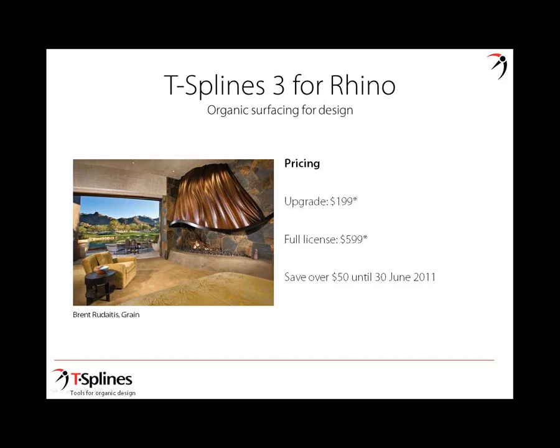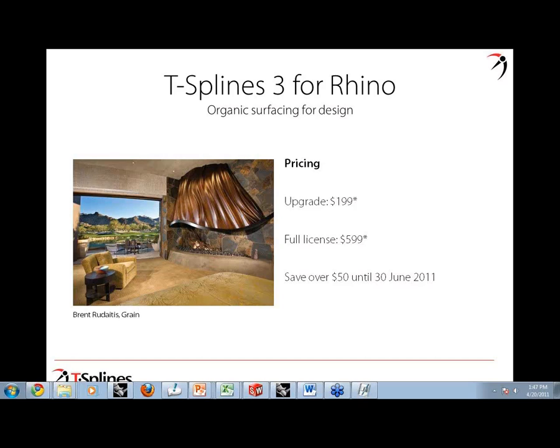If you're CNCing, you're not going to have to worry about Z dives through the part because there's no gaps. And if you're going to RP, you can just send it to a service bureau and not worry about anything being wrong with the data because the stuff is really good. I've done a lot of parts using T-Splines data and never had a single one have an issue. I've had junky NURBS data that I've built have problems, but I haven't had any with T-Splines.